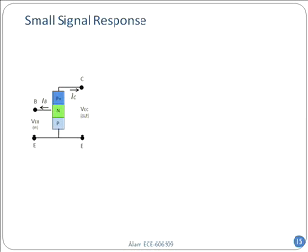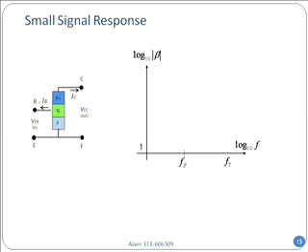So what I want to know is, actually I have a great DC gain, that it amplifies the DC current well, but do I have a great AC gain? That is, if I have a small signal coming from a radio station, what is the highest frequency that I can amplify? If you try to do that, you will see that when your frequency is low, that's the red curve, and the x-axis is f, the y-axis is log of gain. When the frequency is low, the DC one, well, that's great. You have a lot of gain. So it could be 100 or 1,000.